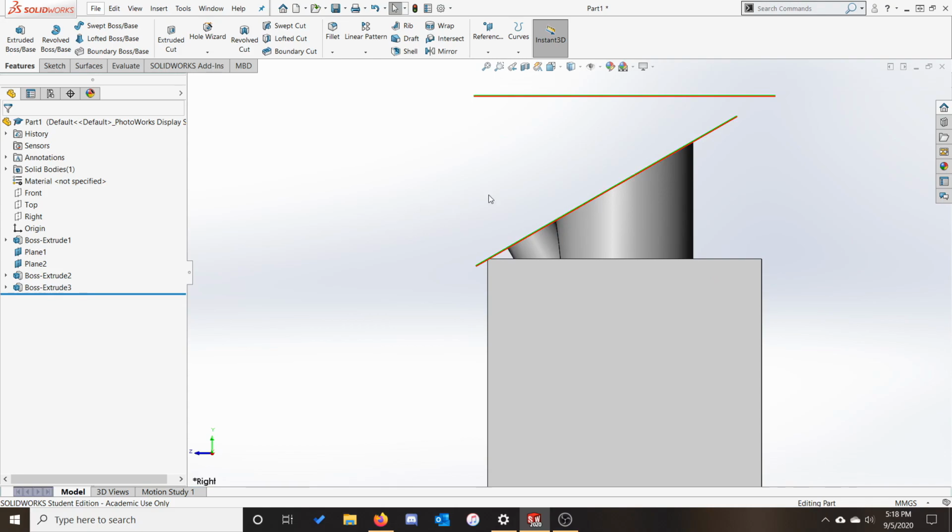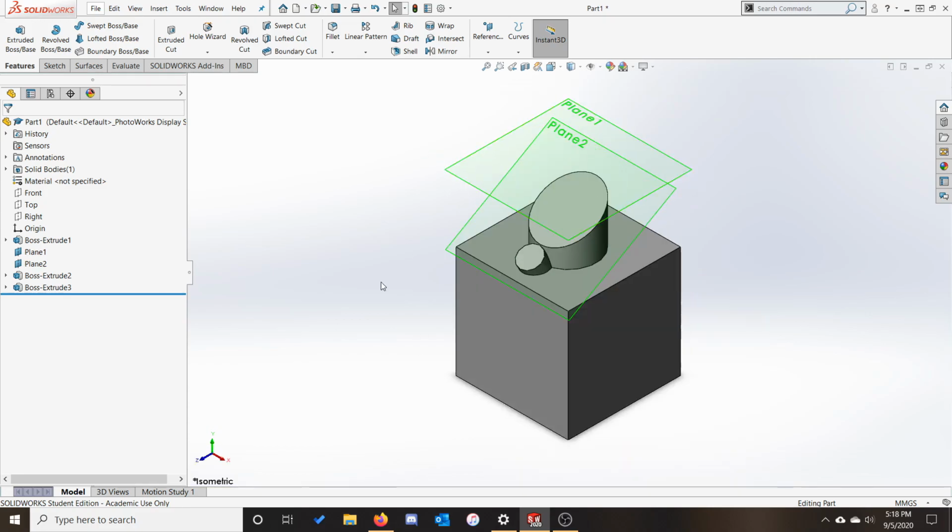This is important to remember when starting your sketches to make sure that the resulting features turn out the way that you expect. So, that covers several ways that we can create and use reference planes. What other methods can we use? A common one is to define a plane using 3 points. Here, we're going to need to define our 3 points for the plane first.